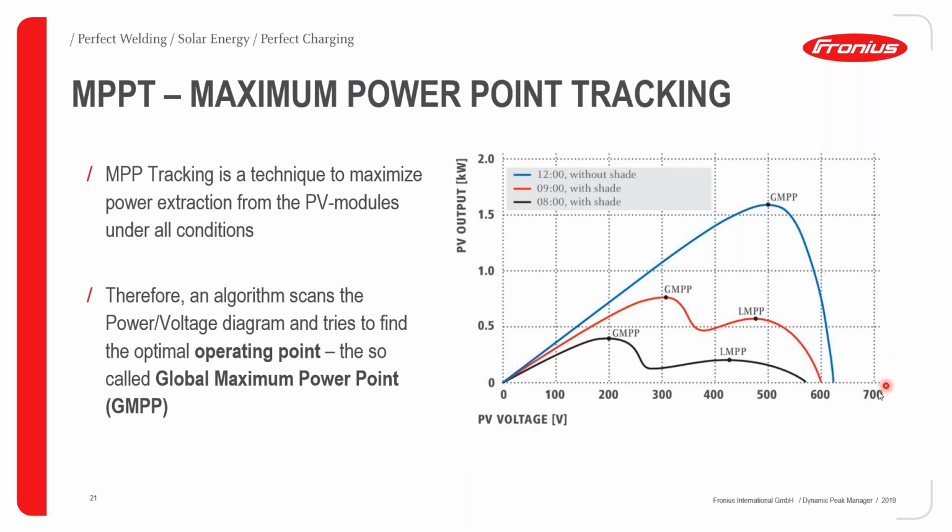So as already mentioned by my colleague, highlighting the maximum power point in an IV curve or the power voltage curve of a PV module, most of these gadgets are looking for the best operating point to deliver as much power to either the batteries, if you are charging batteries, or to whichever loads are utilizing that power at that moment.